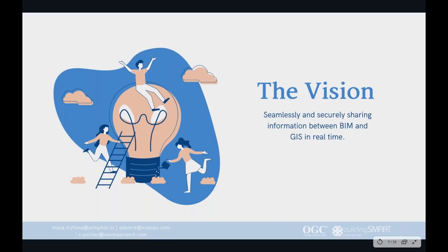The next step is, if we transport information from BIM to GIS, we want to get the whole semantic from the information as you got inside BIM. This means you need a centralized data dictionary, and you need the possibility to declare content in BIM exactly in the same way as you can declare it in GIS. For that reason, we need something to transport information in GIS element-based in a nearly same way as you can do it in BIM. And the solution for this is CityGML.